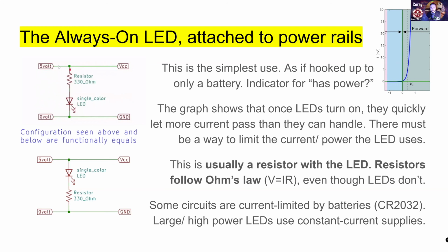If you wanted to play with this, if you have these things sitting in front of you right now, you could plug your Arduino into a computer, plug the resistor into 5 volts and the negative side of the LED into ground, and then touch those two leads together and use the Arduino as sort of a power supply right there on your bench top. So this is a good sanity check to see if this is working.